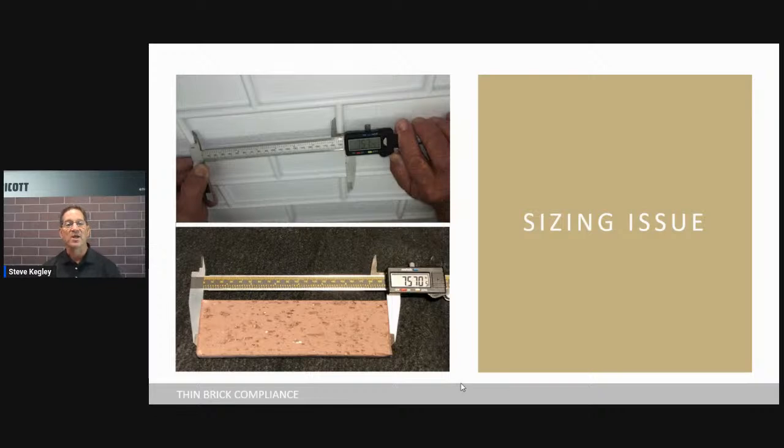Okay, and when orders come in and they get manufactured, I don't know of a thin brick company that doesn't work with the form liner, provide them a sample so that they can match up the thin brick out of the run, maybe 24, 30 pieces with their form liner, make sure everything's right. And you should do that as a best practice.